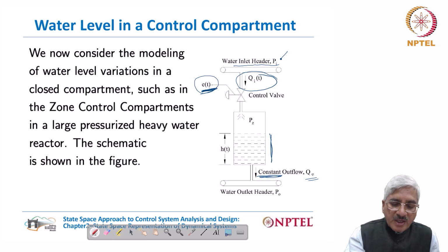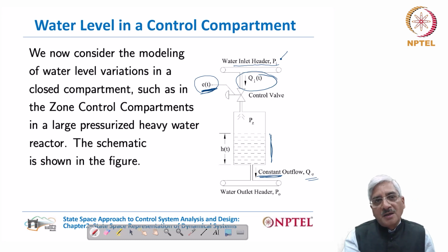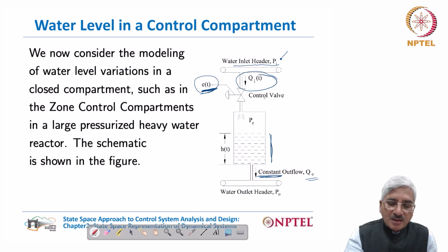This pressure change on the diaphragm of the actuator results in changes in the force on the moving parts, and thereby the valve stem moves, either it opens more or it closes more, and when it is constant, then the valve remains at a constant position.